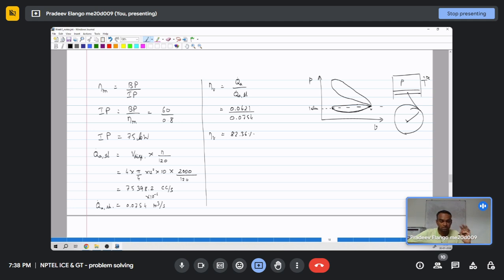And this is giving us a power called brake power. If you assume some imaginary pressure which is applied on the piston throughout, and this pressure is constant, and this constant pressure can lead to the same brake power, assume the mean pressure that we apply gives out the same brake power, then that pressure is called the mean effective pressure.